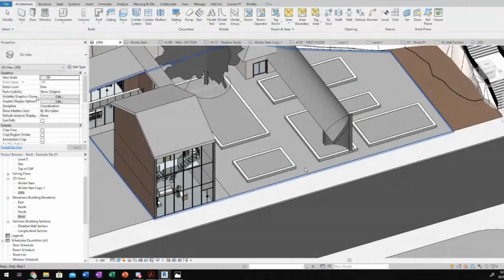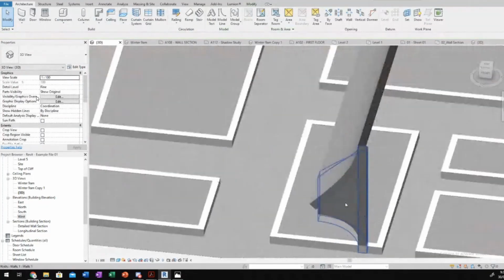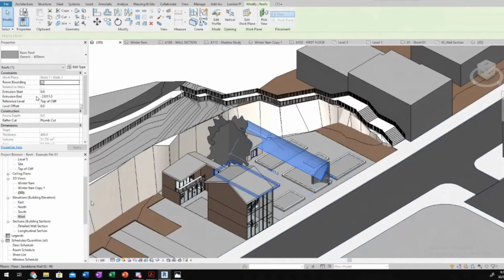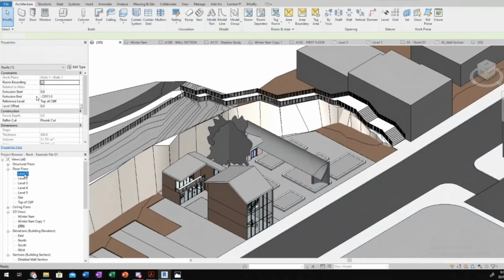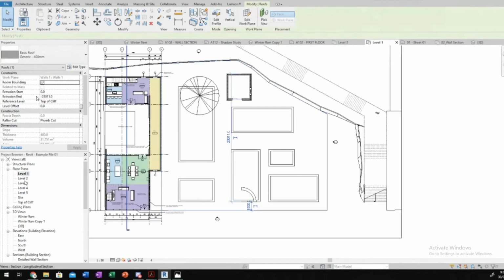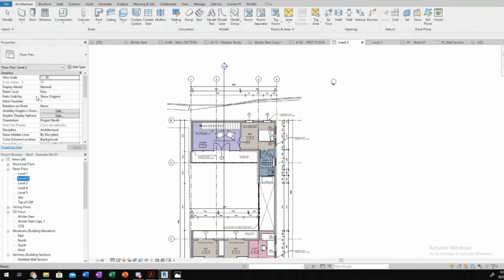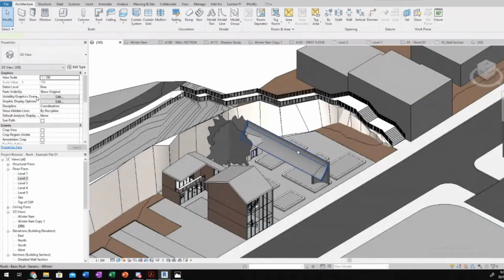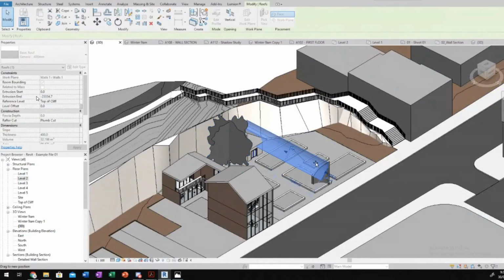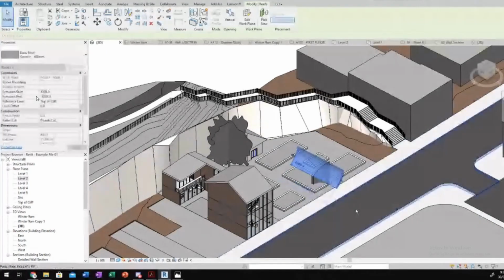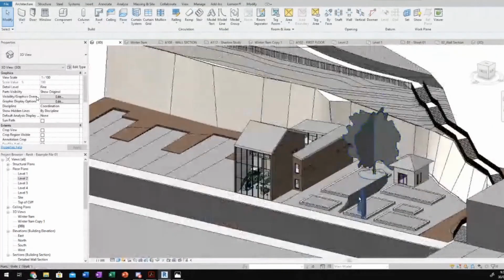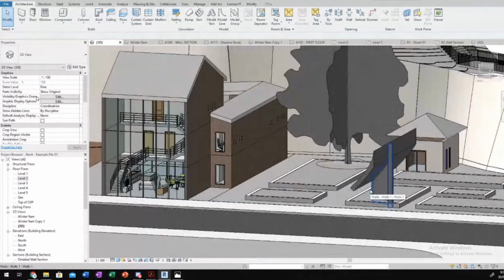There we go. And if we go into 3D, it's a little bit funky, but can you see how it has taken that curved shape? So let's just go, where is it? I think it's level 2. Not quite sure, but we need to fix the view extent. So if we click on that, look, we can drag this. So that kind of works, yeah? Like you can see how we've fitted it to that curve.